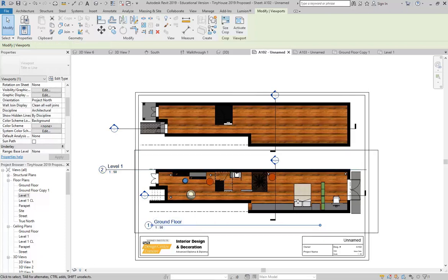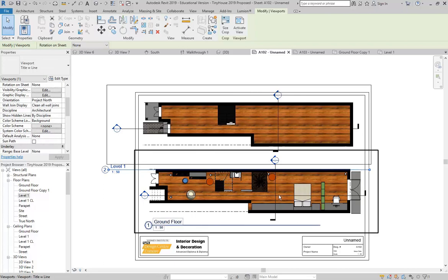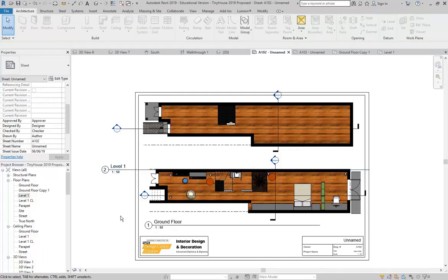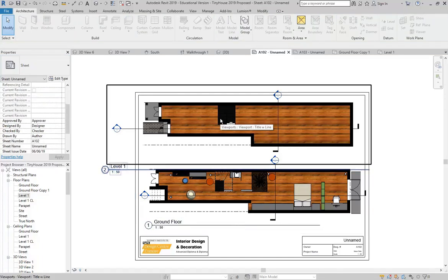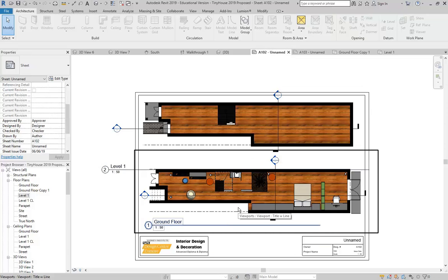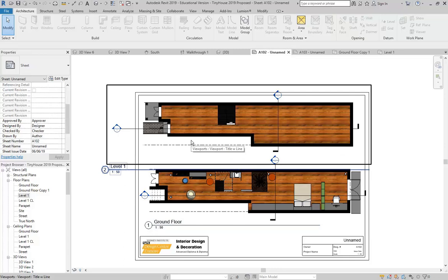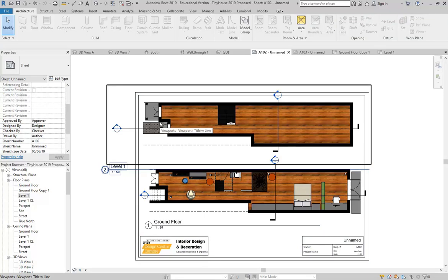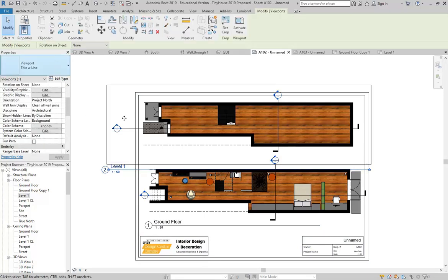Right, so what I wanted to really show you though is the order, because it's not obvious and it took me a while to realise how they should be, the order that the views should be. So if you were putting two plans on a sheet, which one would you have at the bottom? Ground, you'd think. But then how do you read? Top to bottom, left to right. So what I used to do when I first started uni, I used to put ground floor at the top. And then I got in trouble by the people who, back then you had people whose job it was just to check drawings. And I got pulled up straight away and they said, no, don't be stupid. It goes in the order you build it, which is again the way you were saying. So ground at the bottom and then you stack them up.